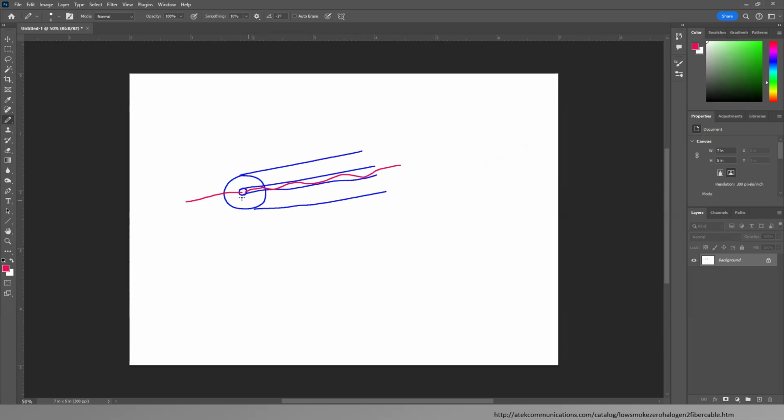Now, the signal travels because of something that's called total internal reflection. We need to establish a total internal reflection inside the core, so the signal, or the light pulses, light modes or beams, otherwise reflect from the interface, and the interface is the point where one medium is interfaced with the other. So here is one type of glass, here's the other type of glass. The core has a higher index of refraction, which means it slows the light more.